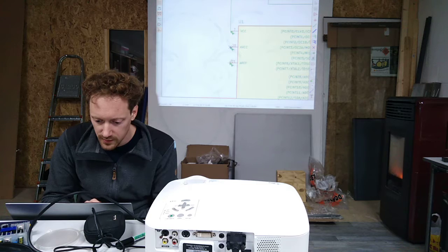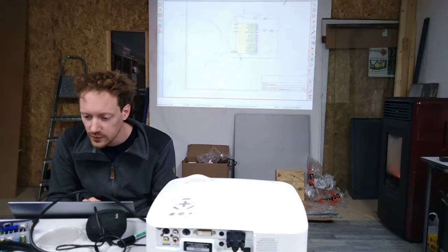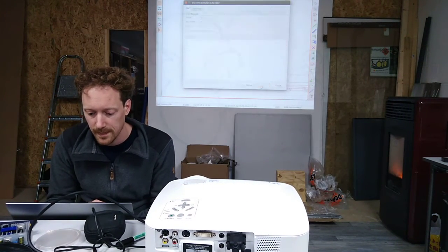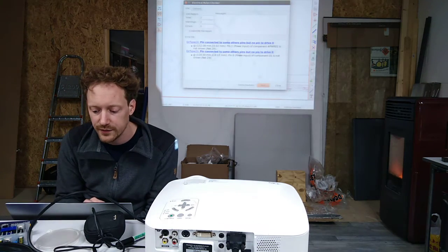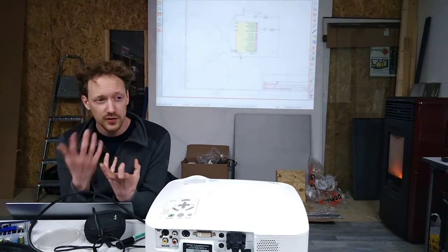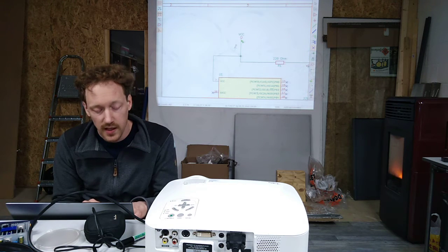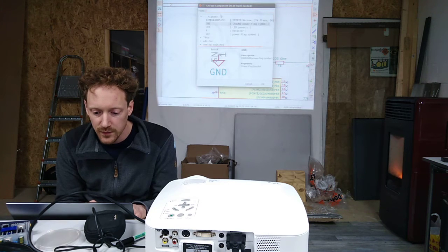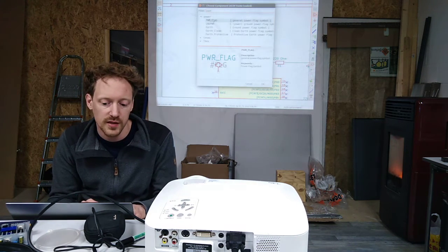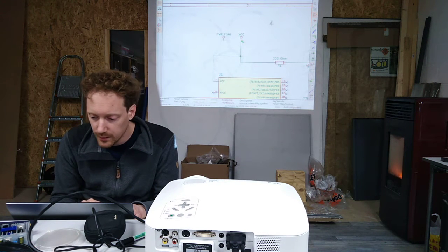and there and there. I think I crossed all the components out, and I'm going to run the verifier again. And it says, oh well, pin connected to some other pins, but no pin to drive it. So you basically have to tell KiCad what power and ground is. And you can do that by adding a component again with A. It also shows the arrow where you have to do that. So now you have to find power flag. And we add power flag here, connected to the VCC.